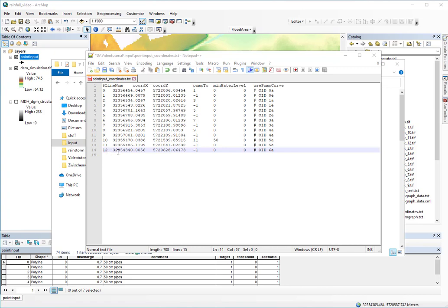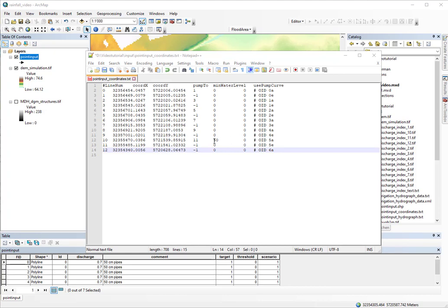And here you can see our line number 12 has only a beginning but no end coordinate, because there's just water being extracted. So that you can also see here, because at pump 2 there's only a -1 and no different line specified where the water should end. And the last special feature you can see here is at the minimum water level column, that down here at our pond line the 50 centimeters is specified. So that's everything included in our coordinate file.